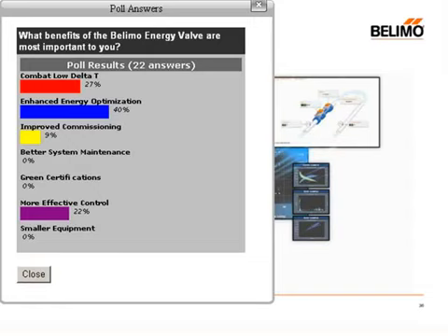Okay, we have one final question here as we're at our 3 o'clock. The final question is from Keith Dougherty. Any calibration required for flow sensors or actuators during install or years following? No, there's no calibration, and there is no maintenance required on these. As we talked about earlier, the flow sensor is an electromagnetic flow sensor with no moving parts, so there's nothing in there to get clogged or jammed.